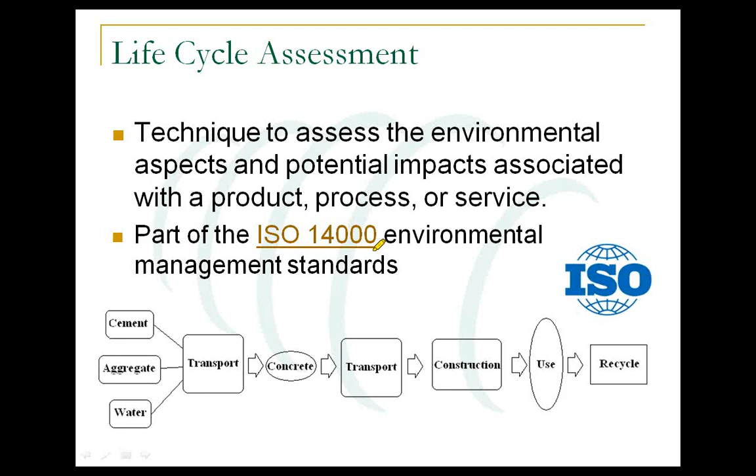Now, for a cradle-to-grave type life cycle assessment, you would go all the way from extraction of raw materials through the manufacturing process, through transportation of the product to the different stages of manufacturing and construction for construction products. And then the use phase, there are impacts throughout the use phase, maintenance perhaps, or other processes throughout the entire life cycle that you need to take into account. And then finally at the end of its useful life, whether it's landfilled, recycled, reused in some way.